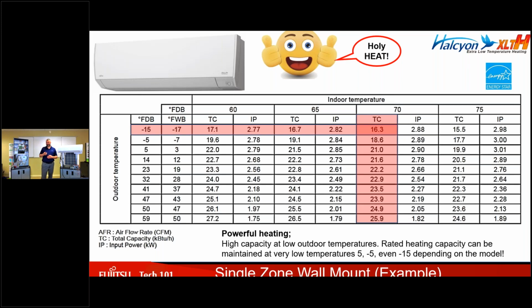And if you take a look on that chart at 14 degrees with a 70-degree indoor temperature, this system is capable of producing 21,600 BTUs.